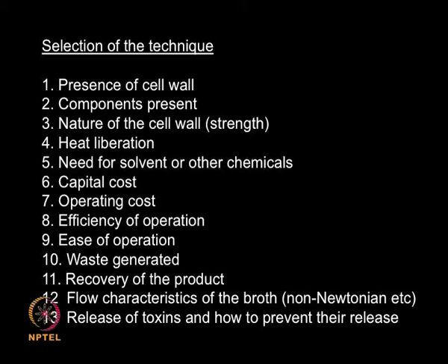If you are going to do it in many passes, obviously the operating cost is very high, so that is not very favorable. So if the efficiency is very high, then you will not have many passes. Ease of operation, how easy it is to operate. I am going to talk about the bead mill, where the operation is very problematic. After the performance, you need to wash the setup, remove the beads and clean each one of them. So the ease of operation is very, very important.